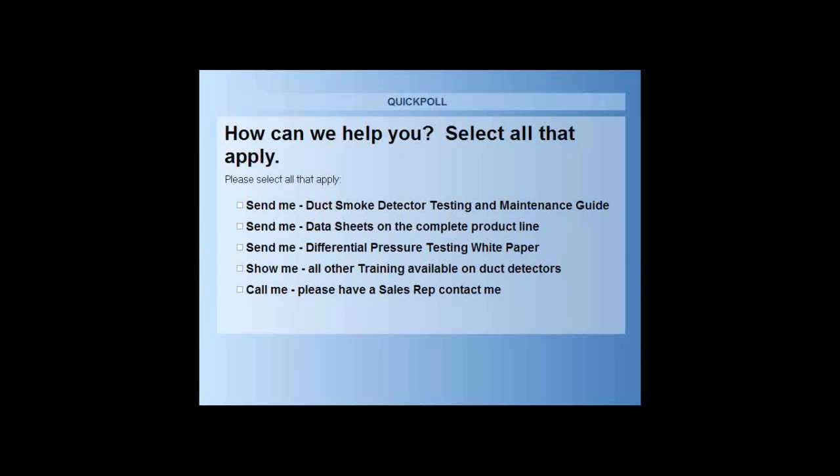If you are using a DNR intelligent duct smoke detector housing, on the power side there is space on that section for an intelligent module to be installed in the housing. The module does have to be purchased separately, but there's space for it in the housing. Once you have that installed, you can use it for shutdown.